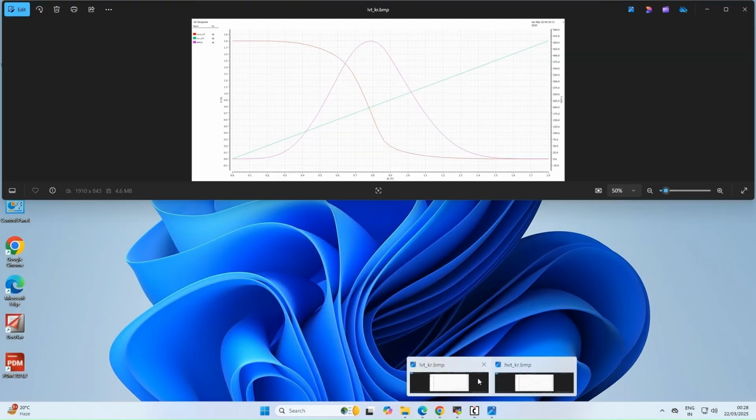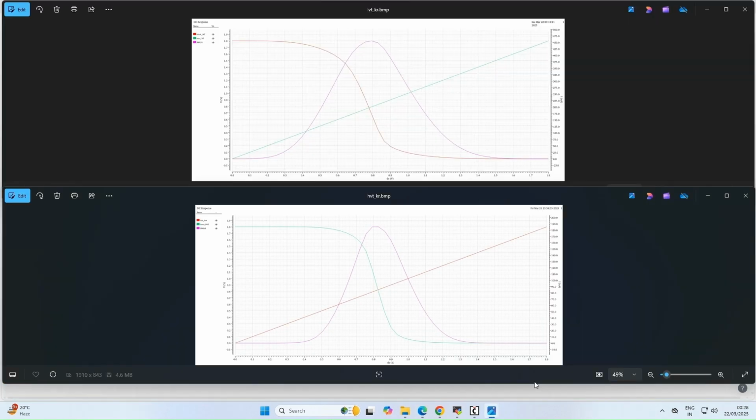On the other hand, the HVT transistors are more power efficient, but they switch at a higher input voltage also, and they may introduce delays in our design because obviously the switching voltage increases. So the choice between HVT and LVT will depend on our design, whether we prioritize speed or efficiency.